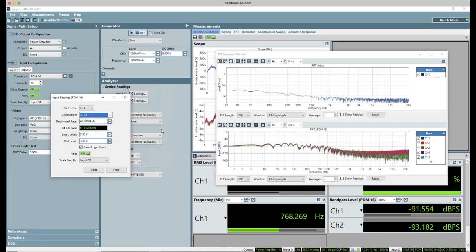So that actual bit of mathematical magic is a bit above me, but I'll give you the textbook answer, which is that we do this comparison at a very high rate, so exactly maybe 3 megahertz, and we have a mathematical algorithm, a set of feedback and feed-forward loops that push the quantization noise produced by that up above the frequency range of interest, or the audio band, for our applications. So there's a bunch of energy up above 20 kilohertz.